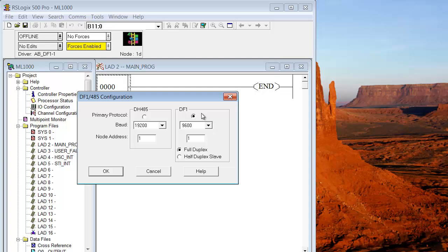MicroStarter Lite, by way of RSLinx, sends a message out on that driver, out the COM port. It sends it out at a specific baud rate, parity, stop bits, etc. It sends out a message at a particular configuration. If it doesn't hear anything back, then it changes one setting and sends it out again, and it keeps changing settings one at a time until it hears back from a processor out there.